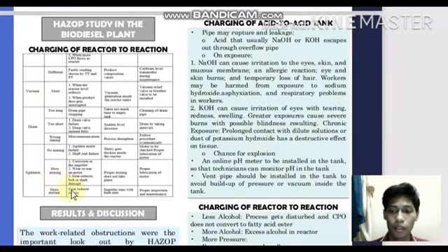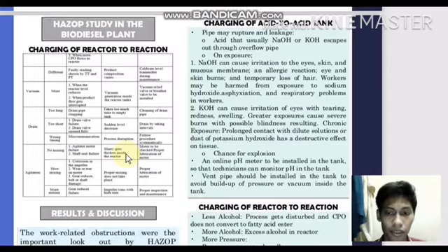And I also want to mention about the agitation. If there is no mixing, that means the agitator motor has failed or the shaft seal has failed. If the agitator does not function well, the slurry will get thicker inside the reactor.